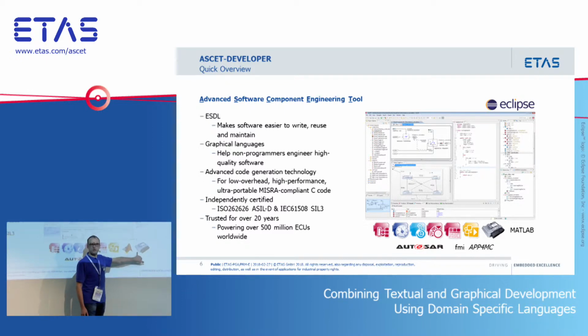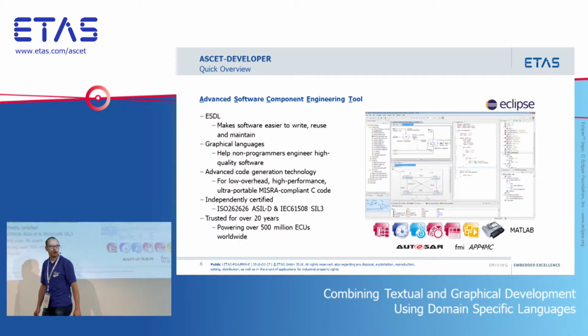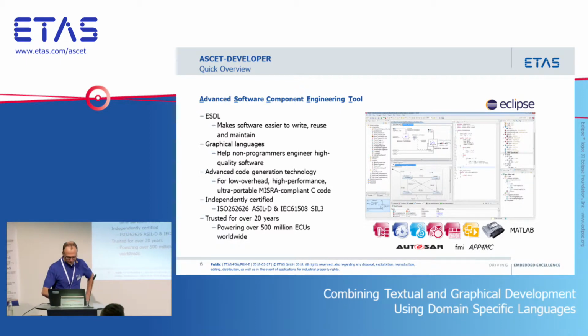And we can just generate code that you can compile up and run on a bare metal ECU with no additional support other than an AUTOSAR or OSEK operating system. And it talks AUTOSAR, and it talks FMI, and it'll talk APP4MC if you're doing things like multi-core distribution and things like that.